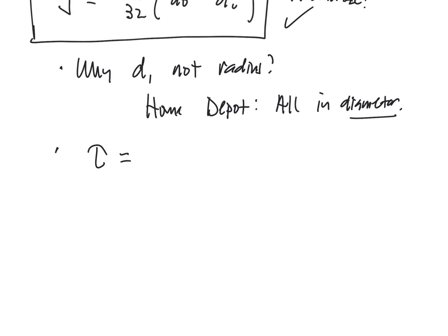We have the shear stress is equal to torque times rho divided by J. Notice a couple of things. First off, that it is linear. So I'm going to double bullet this. It is linear in the radial distance. There it is. Rho is just sitting right there. So we've got that aspect of it.